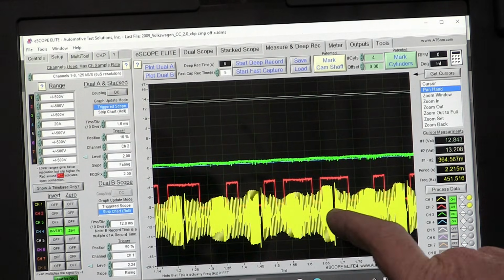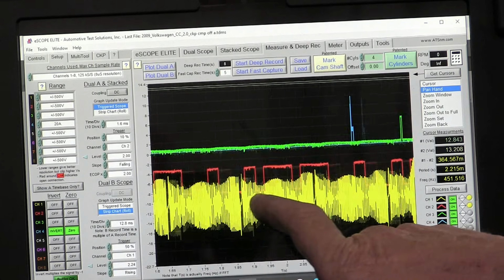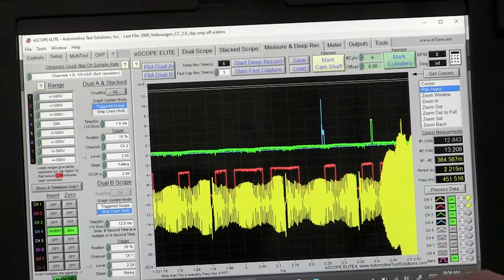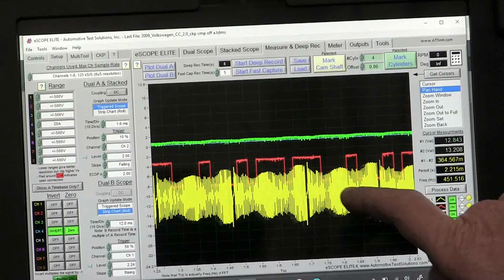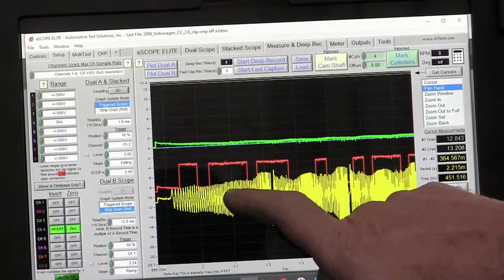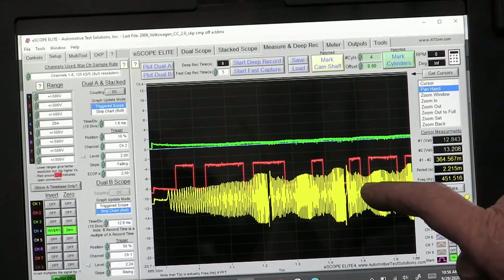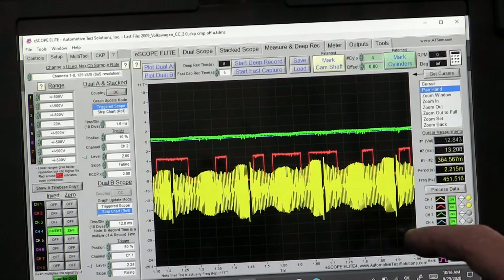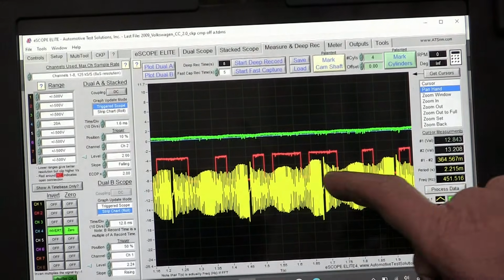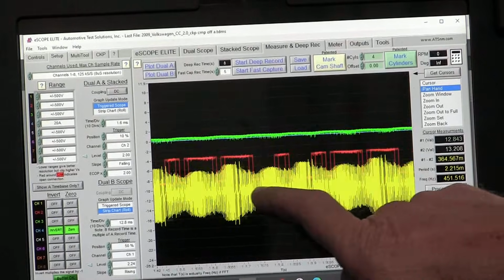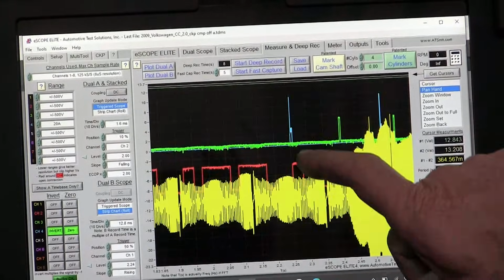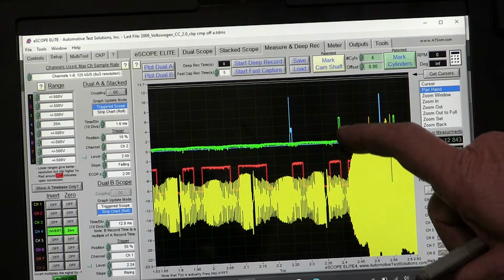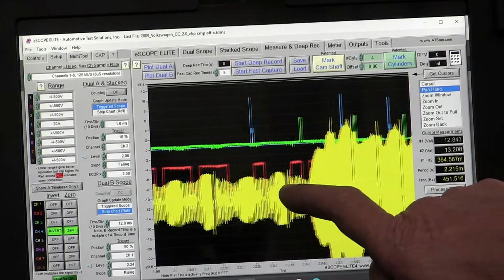I had a second full revolution, a third, a fourth, and in the fifth I finally could find the timing. Now, when you are looking at these starting, these should start within 1 to 2 full crank revolutions. I should have commands being put. So right away, I've got a problem with this command. We'll look at that here in a minute. But I want you to see how long it took to get the injector and the ignition coil to fire.